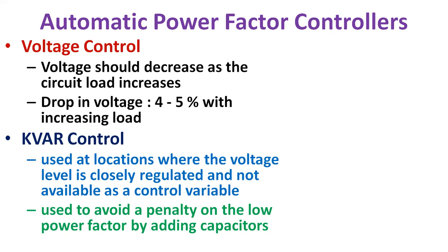Voltage is the most common type of intelligence used in substation applications when maintaining a particular voltage is of prime importance. This type of control is independent of the load cycle. During light load time and low source voltage, there may be a leading power factor at the substation, which is to be taken care of. Then we have the kVAR control, also called